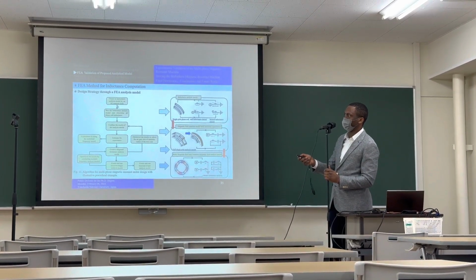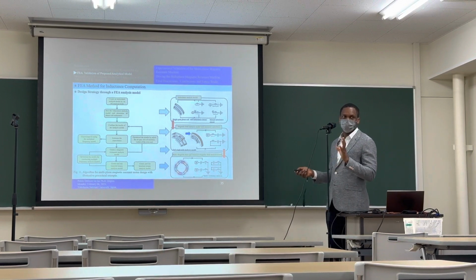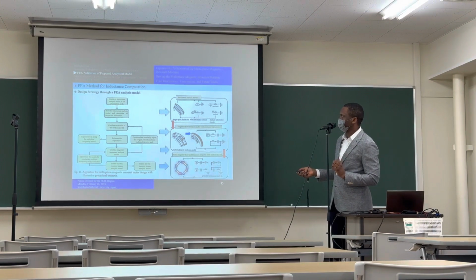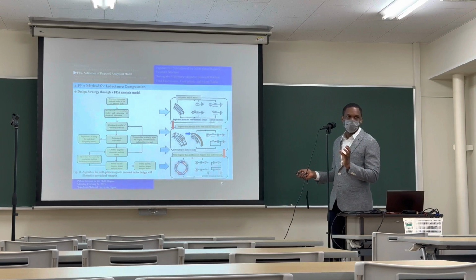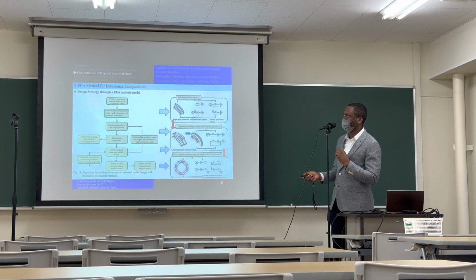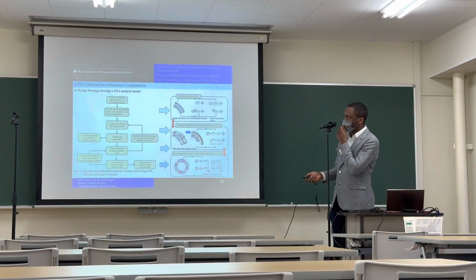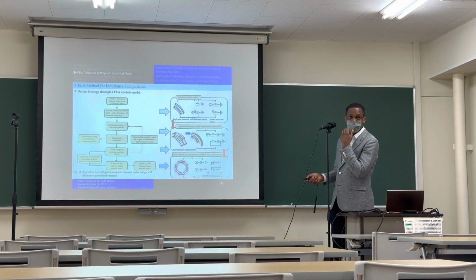The procedure will first create an inductance model. In this research, we use the JMAC analysis tool as the main finite element analysis tool. We take just a single pole coil because we don't need the entire machine; we just need to calculate the inductance of the coil. So we take a single pole, use this model, run this analysis, and calculate the inductance of this coil. When we have this inductance, we determine the capacitance value through a target frequency.